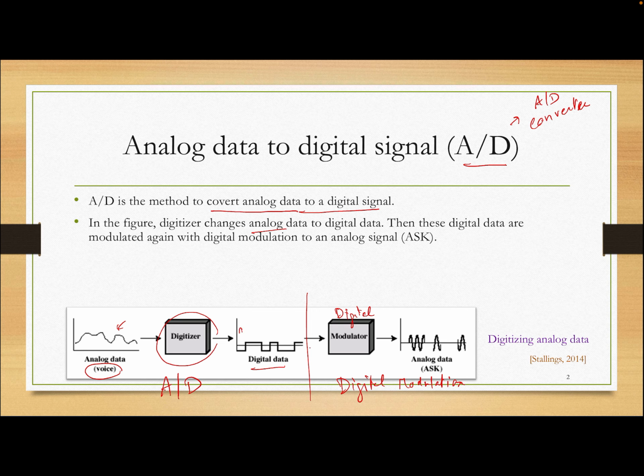This one is, for example, 01101, into analog signal, to be transmitted like ASK here. So basically this is 01101, because for 0 you send nothing. I show you this combination of AtoD and the digital modulation.